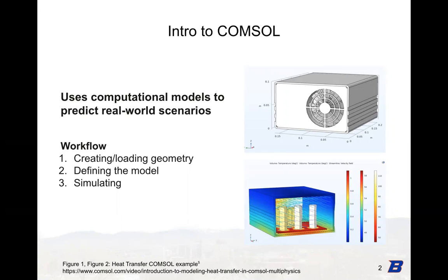The basic workflow that COMSOL users follow is first to create and load a geometry. The second is defining a model, and the third is simulating. And these two figures on the right show the COMSOL model of an electronics enclosure. Loading the geometry was just like uploading a CAD file, and defining the model includes identifying materials used, the enclosure and sources of heat, as well as which direction air is flowing in and out of the system.